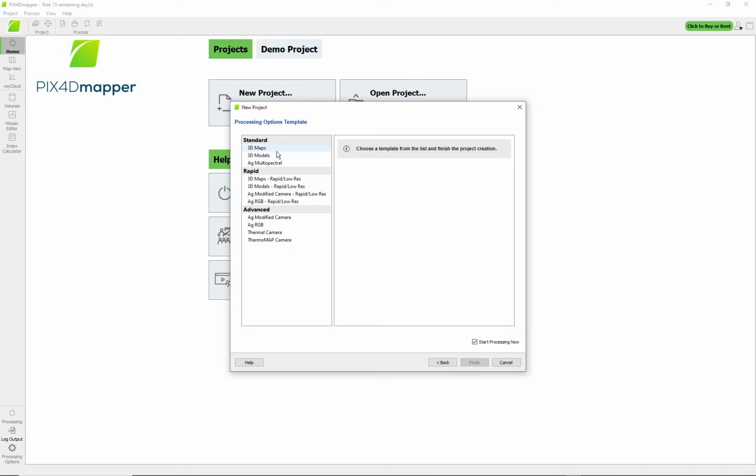Just to finish that thought on the drone photography, one thing that will often happen is that when you're taking off with the drone, you're near a metal object. So once the drone gets up in the air, it should be fine, but you want to definitely make sure that both the compass and the GPS signal are working well when you take off, so that your drone can reliably record its positional data as it's running its flight.